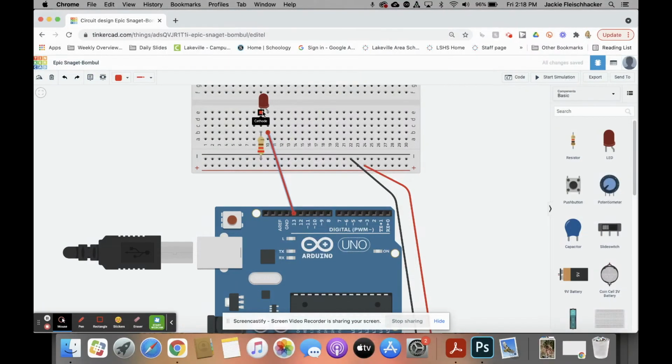So we need to bring in our other two LEDs. So I'm going to plop these in, set up the resistors and the wiring. I'm going to make this one yellow and the next one green. So just like traffic lights, putting our resistors in. 220.